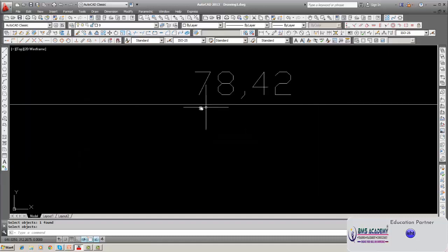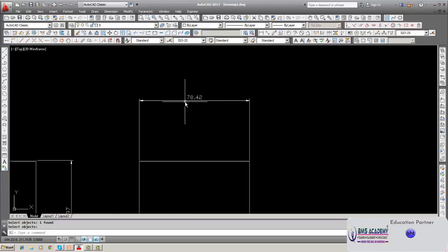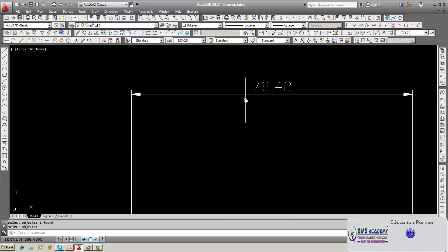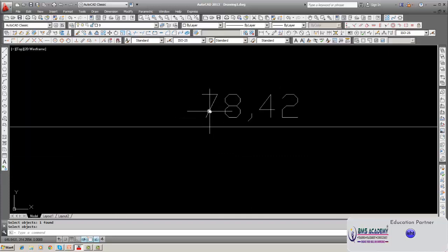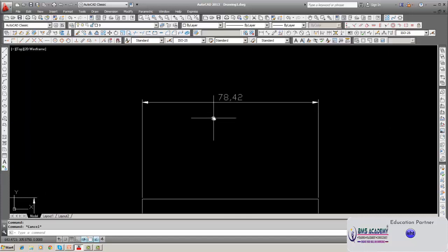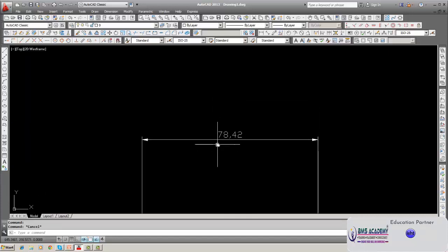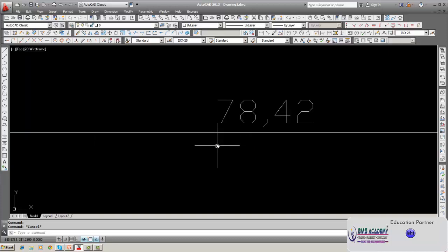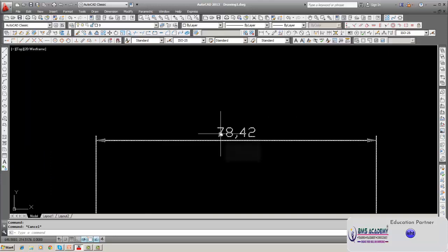The height becomes 27 on the model. But since it will be reduced on the drawing, its size will come down. Suppose this is 2.7; if you want the actual size on the printed drawing to be 2.5 mm height, then it has to be 25 here.